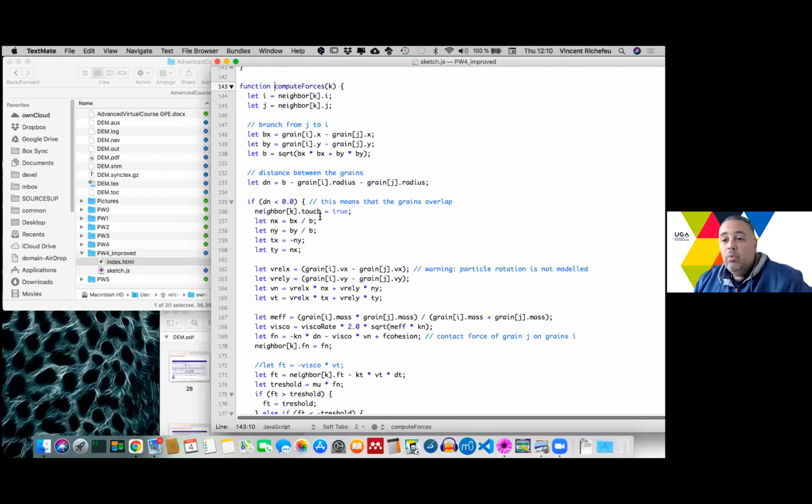Then, depending on what you are modeling, maybe this equation may be due to surface energy. It may be due to capillarity, etc. And in this case, you have to find the literature or develop your own cohesive law, which is nothing else than a negative force added to the normal component of force. That's it. I may suggest a number, but it depends on the physics you are playing with.